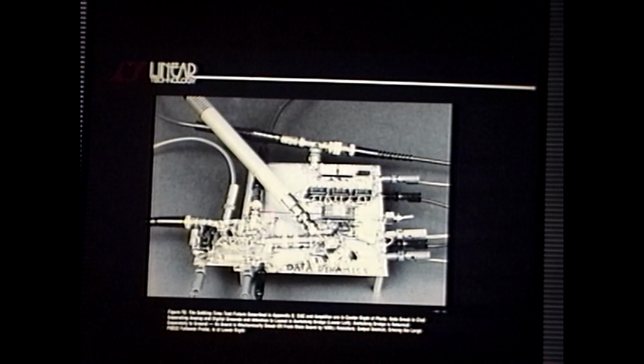See the copper-clad stripe? I broke up the ground plane completely. I don't want any of these digitally circulating currents mixing into this analog stuff here. I pipe the grounding back directly from the digital end. I don't trust the ground plane, as fat as it is, at these speeds and these resolutions. That's what that stripe is right there. I just tore the copper off it.